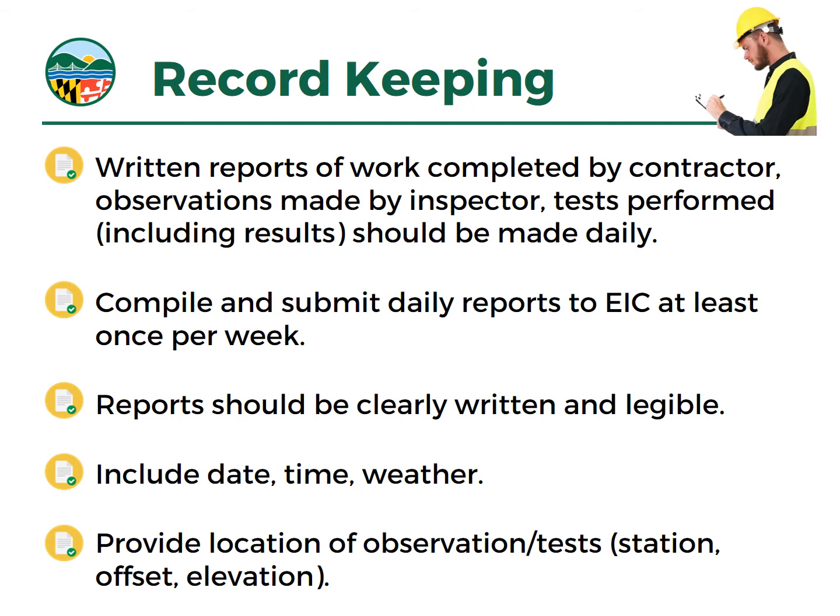And we recommend compiling those daily reports and submitting them to the engineer in charge at least once per week, because that way the engineer in charge can see how things are going, can make sure that any problems are being addressed properly, and if there is something going on that needs some attention or maybe needs rework, you'll catch it before it's too late, before a bad lift of soil is buried under 20 feet of additional soil because the reporting came out a month or 2 months later. We can catch it before it becomes an even bigger problem.